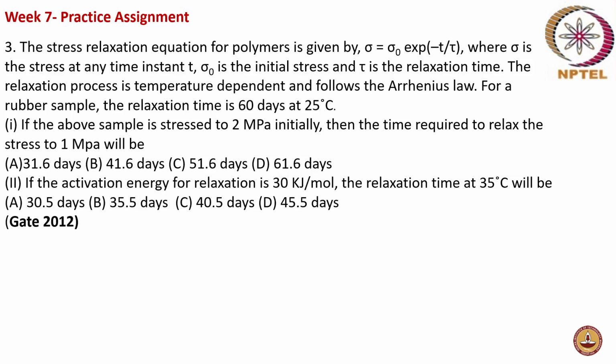The relaxation process is temperature dependent and follows the Arrhenius law. For a rubber sample, the relaxation time is 60 days at 25 degrees.